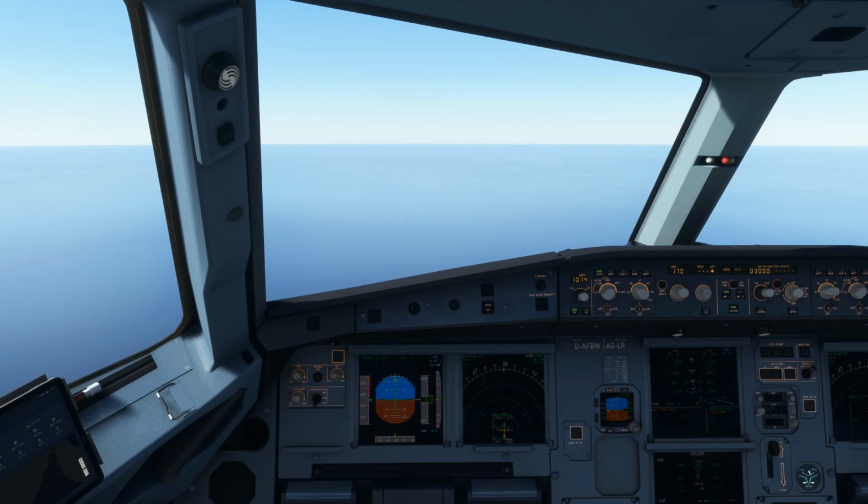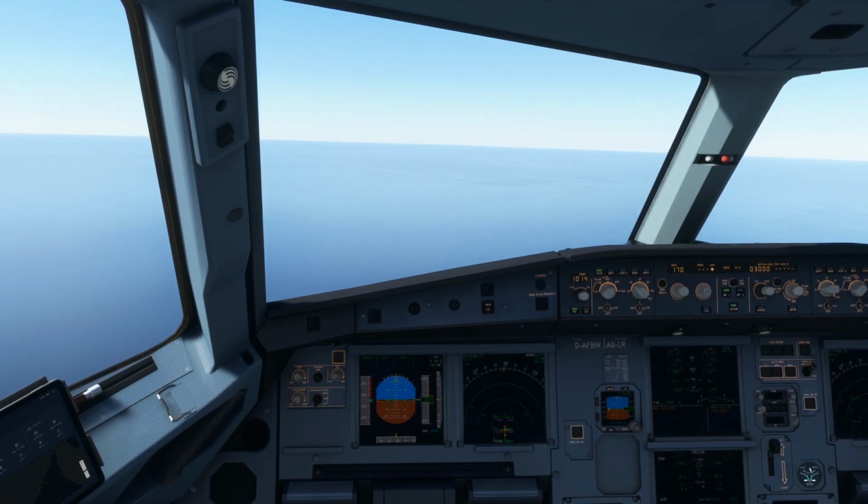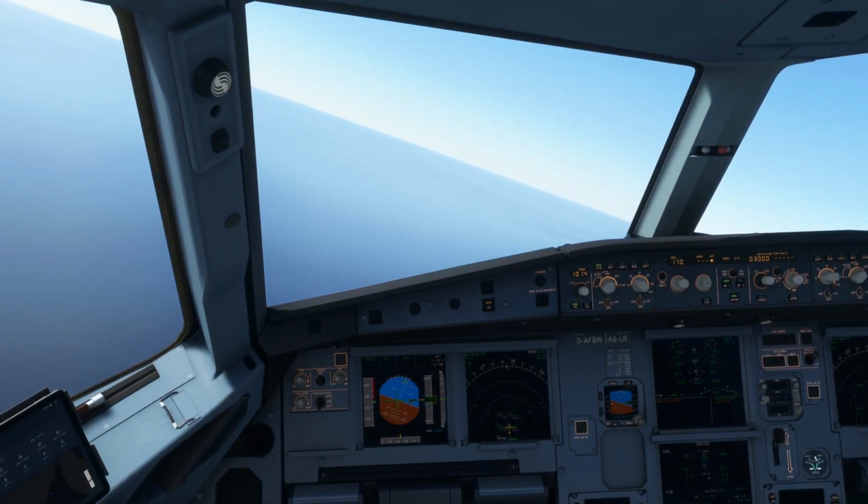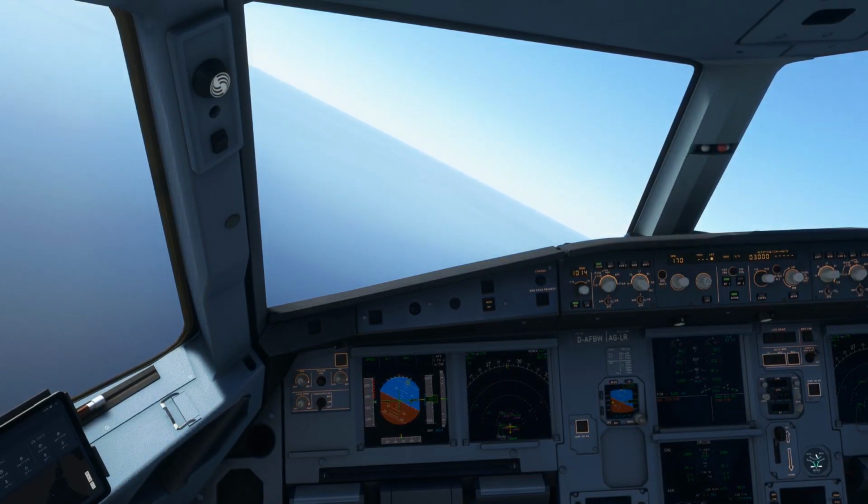But anyhow, as I told you before, I was trying to reduce the speed to a great extent so that the rate of climb is good, so that I am below the given altitude at a certain point. Because as I told you before, in order to catch the glide slope, it's better to be at a lower altitude rather than at a higher one. If you are coming in high, it will be very difficult to control the speed, and your landing can be a disaster. So if you're at a lower altitude, it's good.